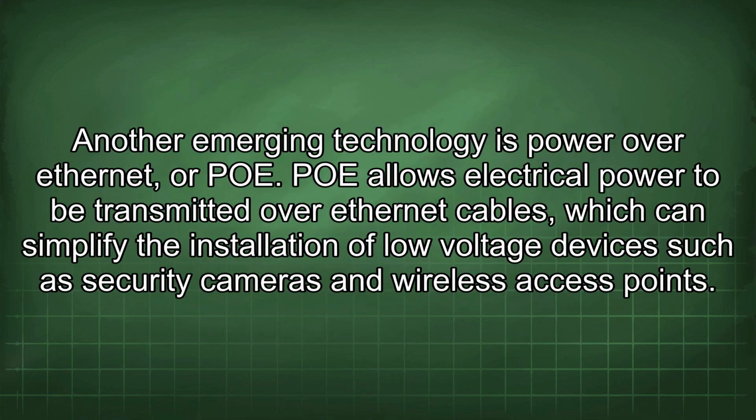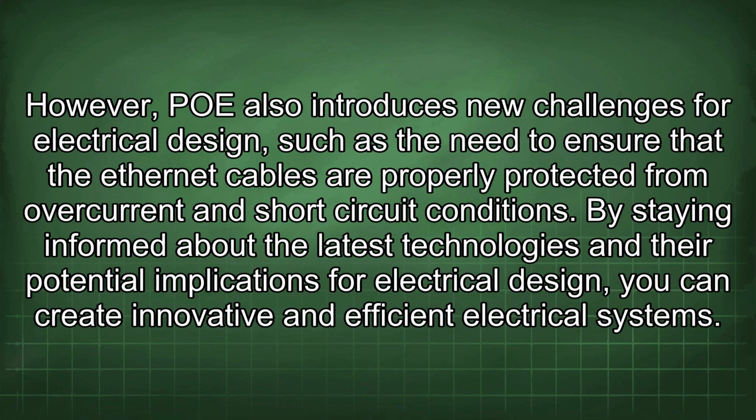Another emerging technology is Power over Ethernet, or PoE. PoE allows electrical power to be transmitted over Ethernet cables, which can simplify the installation of low-voltage devices such as security cameras and wireless access points. However, PoE also introduces new challenges for electrical design, such as the need to ensure that the Ethernet cables are properly protected from overcurrent and short-circuit conditions. By staying informed about the latest technologies and their potential implications for electrical design, you can create innovative and efficient electrical systems.